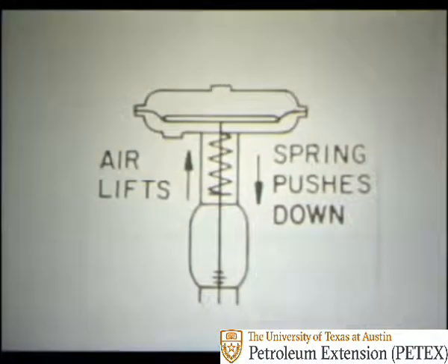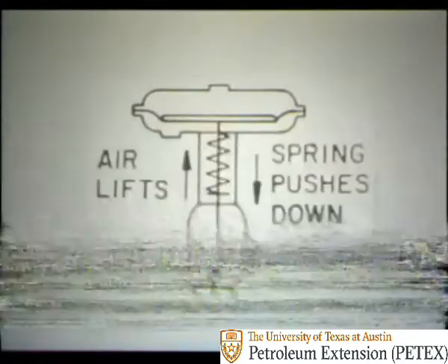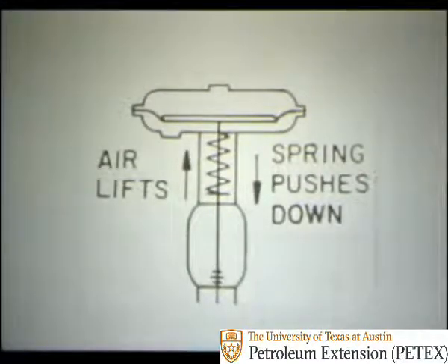Whereas on a normally closed valve, the spring will hold the valve closed until enough air pressure is applied to overcome the spring tension. Note that here the air is applied below the diaphragm. The trim of a valve may be reversed so that the action of the valve will be just the opposite. This now completes our review of the major external features of a production separator.